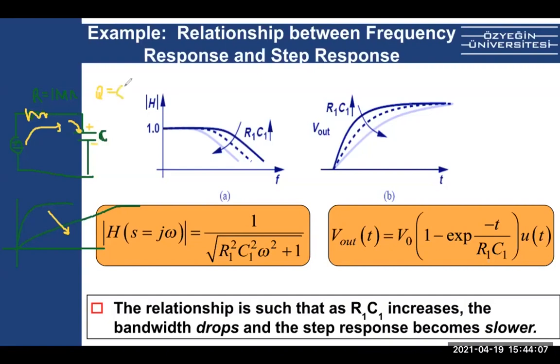So eventually, this cap will come to a steady state voltage, but because this current is so small, we can also write it in terms of current times time, or let's write it as the integral of I times dt. Long story short, because this current is so small, regardless of the size of the C, it will take forever to get this Q. So that means it will take forever to get this voltage. So this won't settle quickly, it will take time.